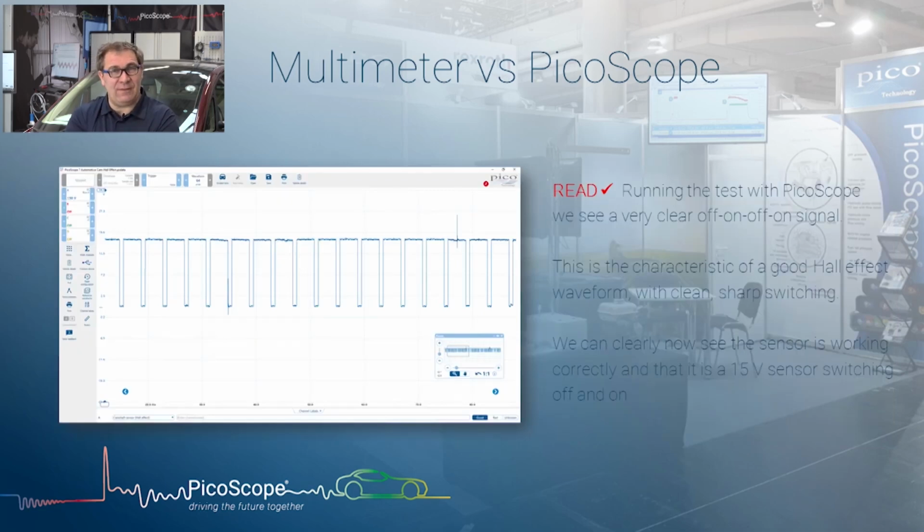And then we're going to see something like this. Not hugely clear on this, and it will be much clearer when Phil shows you, but actually this is a 16 volt sensor, quite unusual in this example. Why does the multimeter say 12 volts and PicoScope's telling us 16 volts? The truth of the matter is, if you look at this Hall effect signal, so it's turning off and on, basically the multimeter can't work fast enough. So it just averages, it just takes the average line. As you can see, in this Hall effect signal, it's more on than off. So that averages out to 12 volts.